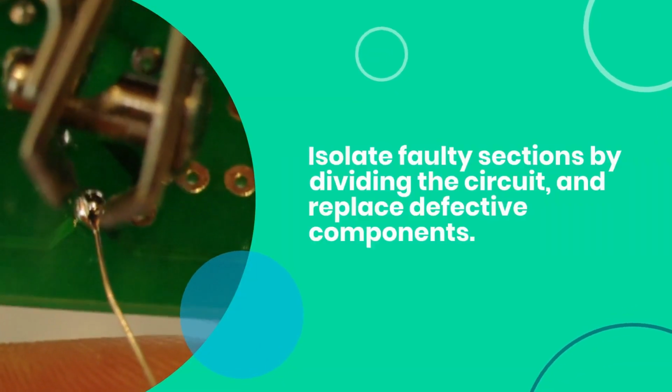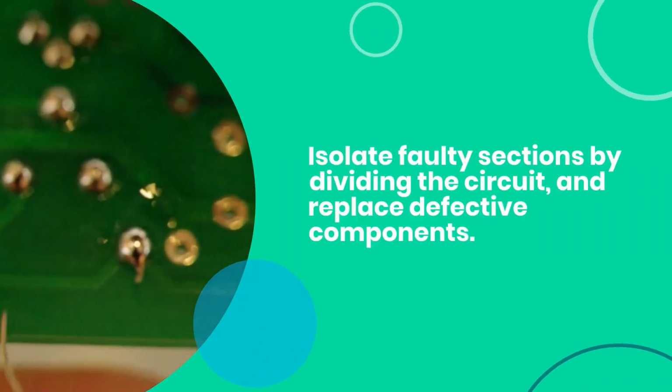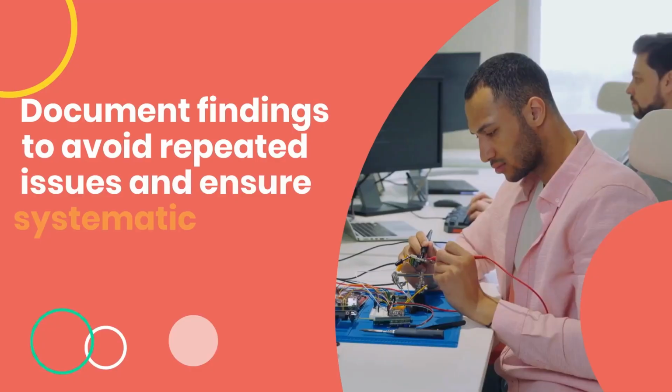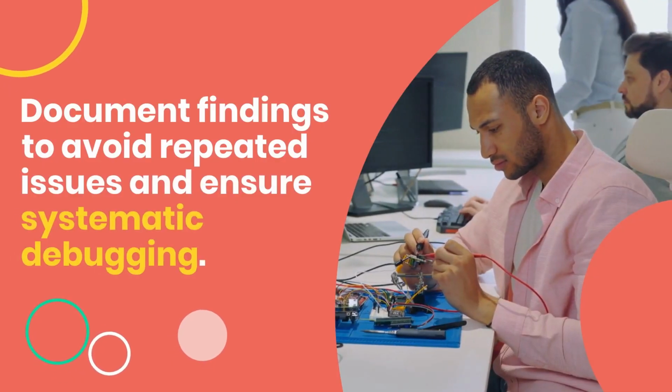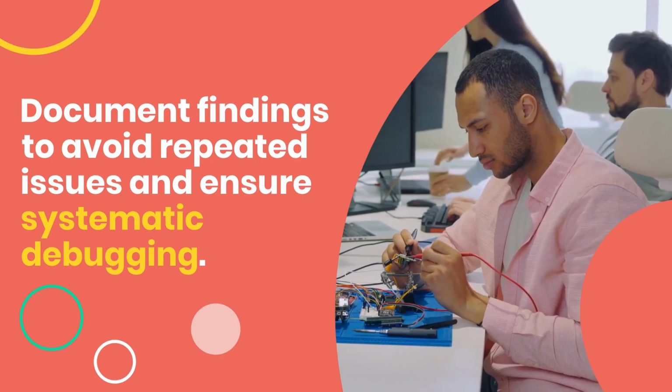Isolate faulty sections by dividing the circuit and replace defective components. Document findings to avoid repeated issues and ensure systematic debugging.